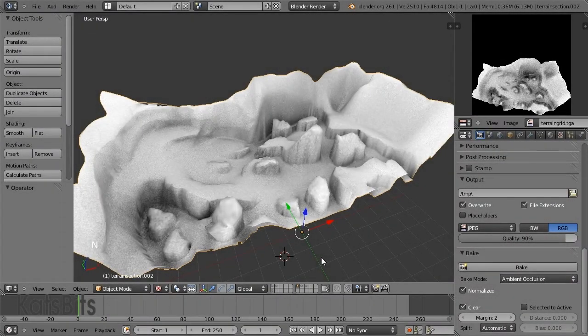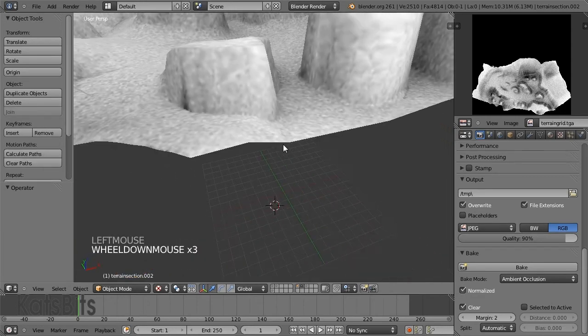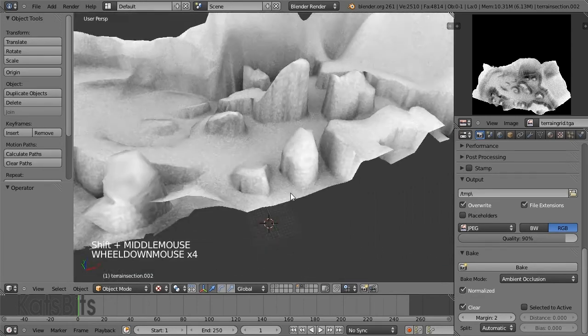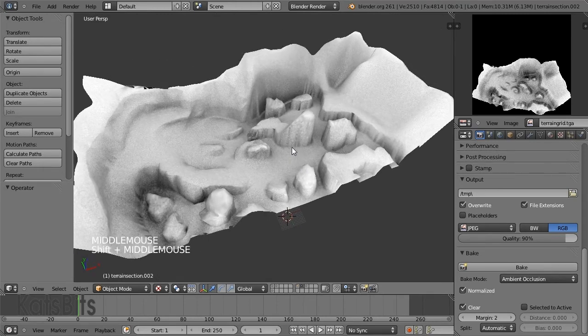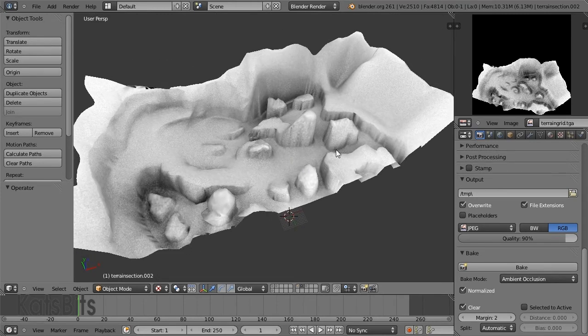Right, there are a couple of important aspects that you need to know when making terrain, particularly because they're such large meshes. The first is literally related to how big the meshes are. We can show this by using a couple of examples that we had that have been made previously. So if we bake a mesh that's large relative to the default grid size, which is indicated here, we won't get optimal results from ambient occlusion.